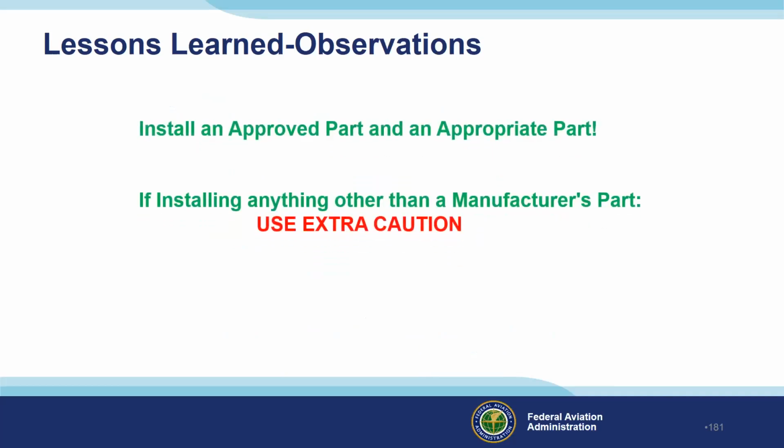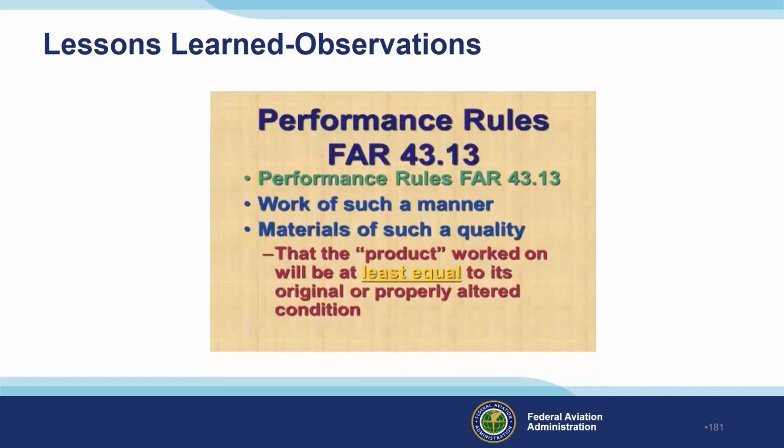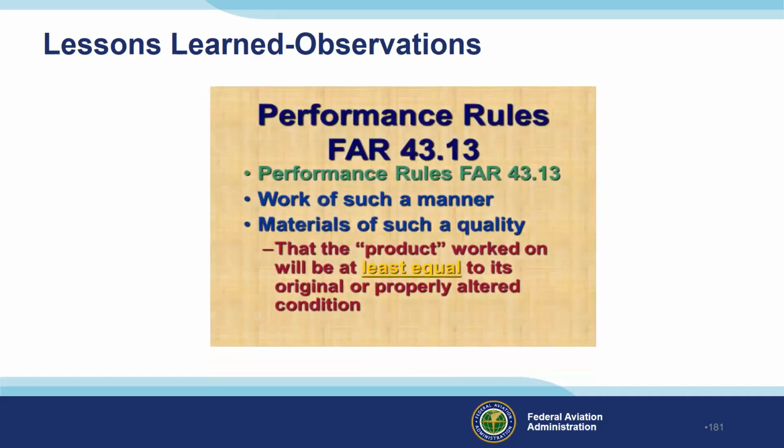Another lesson is not only to install an approved part, but an appropriate part. And if you're installing anything other than a manufacturer's part, use extra caution. Don't forget the performance rules. Has to be at least equal to the original or properly altered condition.